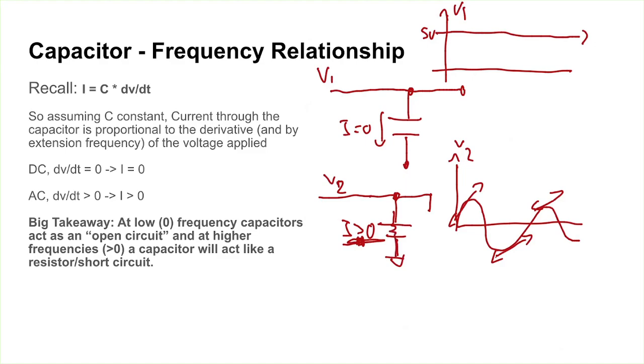And that's the concept of impedance, which isn't super important to us, but it's definitely something worth taking your time to learn, as it'll really solidify this concept even more. So assuming your frequency is going out to infinity, then your capacitor will become more and more like a short circuit. So its essential resistance will approach 0, and it'll just become a short circuit.